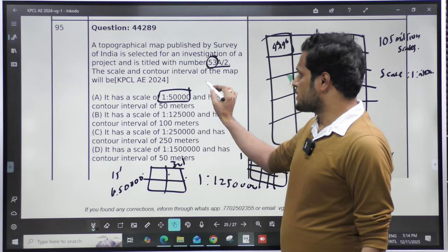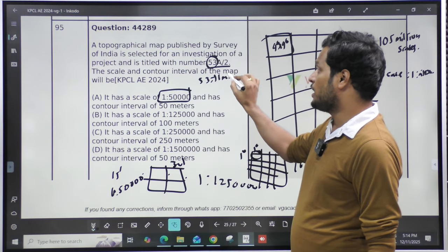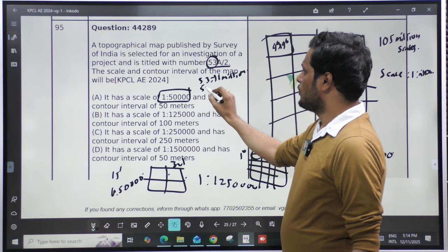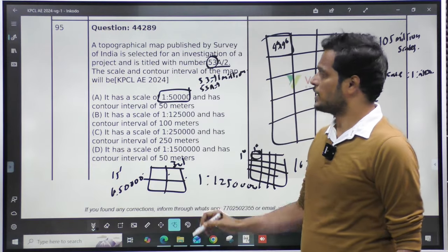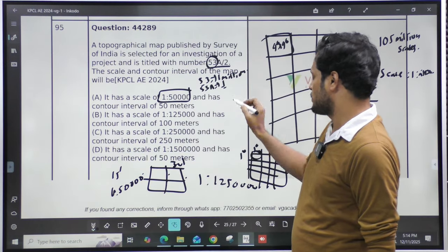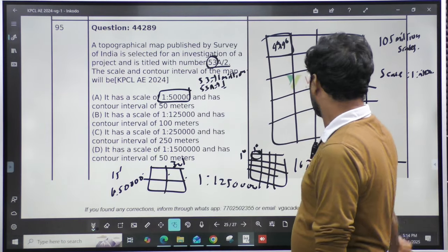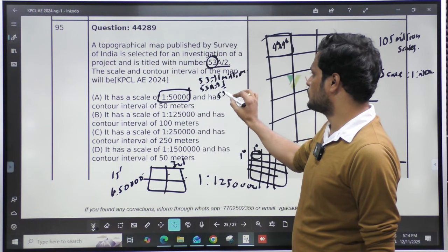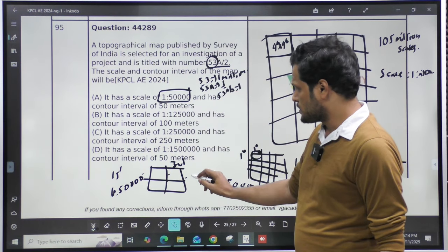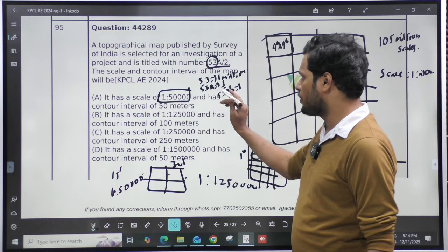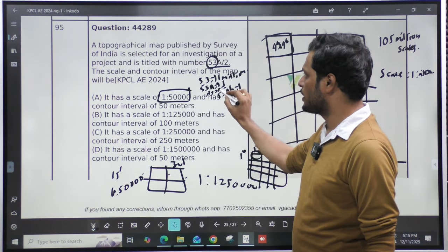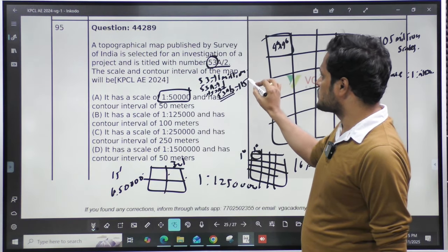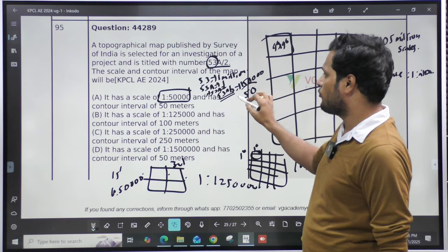If they simply represent 53, it means it is 1 million scale. We have to understand like that. If they give 53A, then we have to understand it is half million, which is 1:250,000. Between 53A/2 and 53A there is one more classification, we call it 53A north, that is not here. So for 53A/2, you will have 1:50,000 scale with a contour interval of 50.